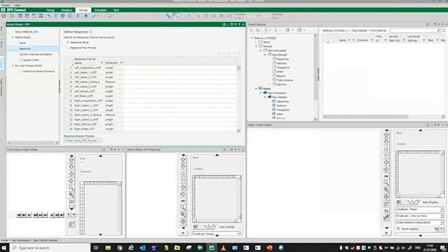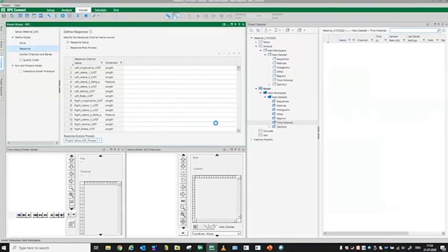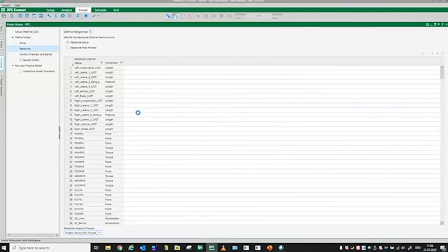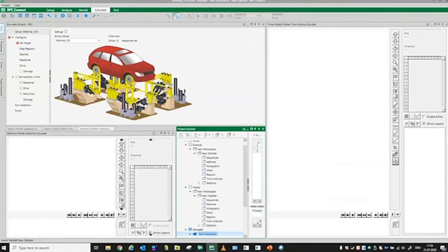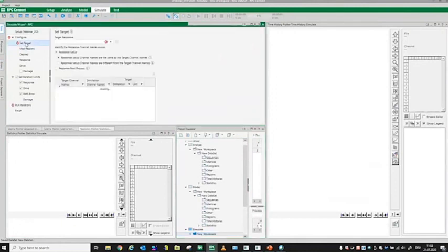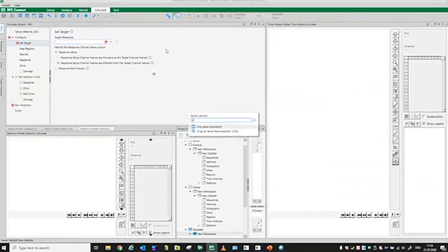That's a good question. I need to check this one out, but as I know, if you go into, let's say, simulate, RPC Connect is now name-based. It's really taking care of the names right now. So if you go in and set your target, you have the possibility to say, okay, if they don't match, let's say I've created my setup with the 48 channels I have, and I know that they are different. You're just going here, and let's make an example. Let's say sine wave.